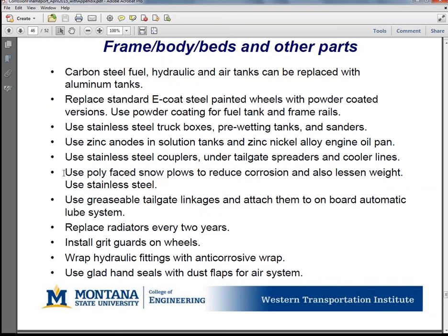Guys were actually power washing so hard they would pierce the covering of the electrical wiring, and it would introduce salt into the wiring and start rusting the harnesses out. So that's the reason we went the other way, because I definitely agree with what Clay said. It's totally opposite of what a lot of car washes do. But low pressure and high volume also creates more of a wastewater issue that you have to deal with, and you don't have an economical way of treating wastewater.